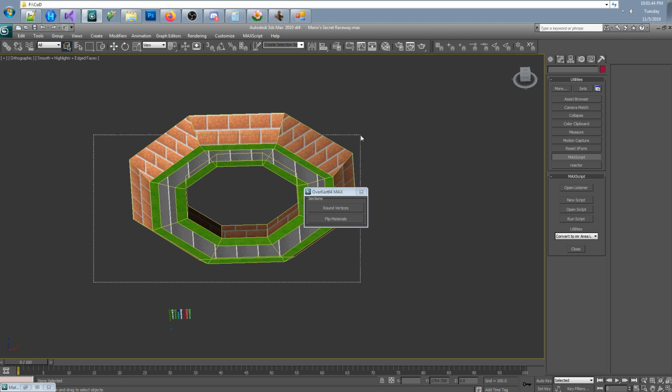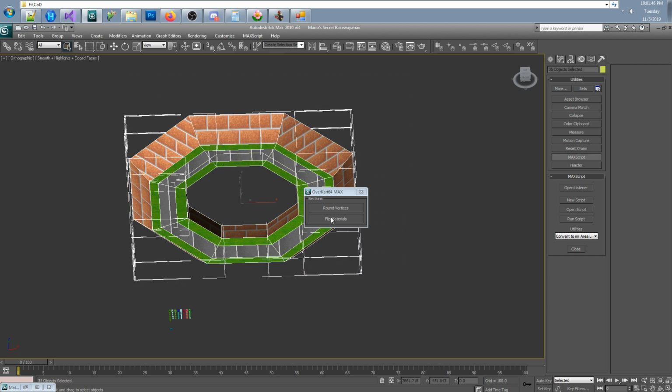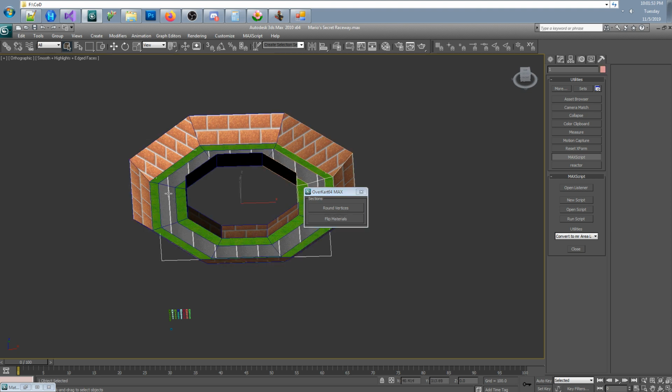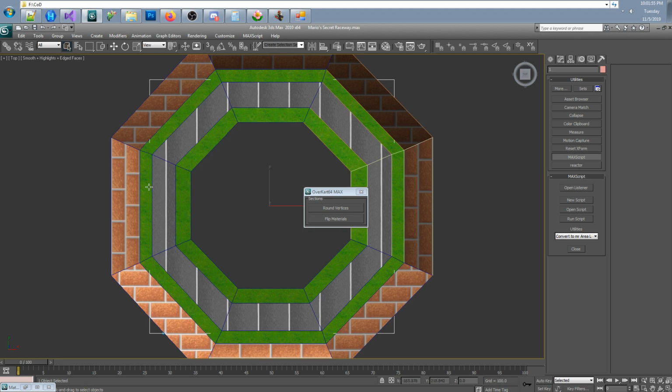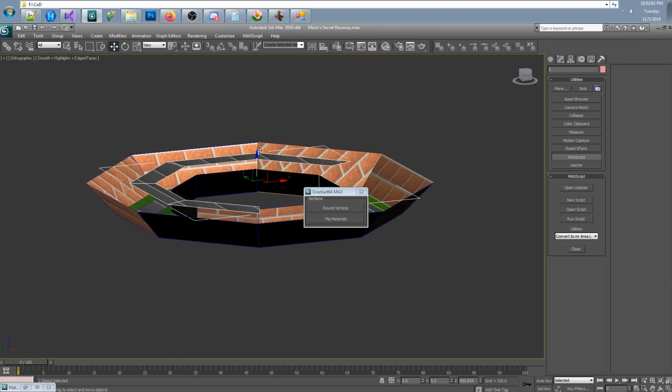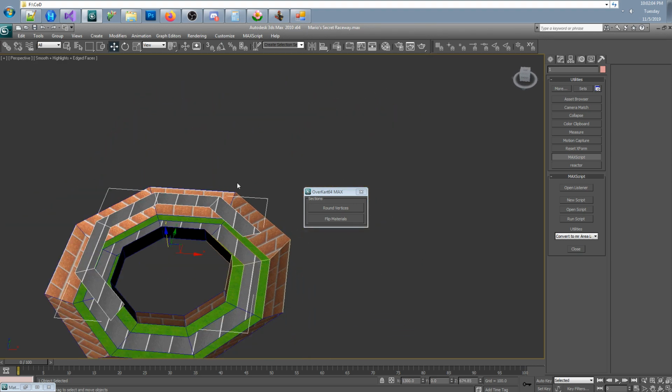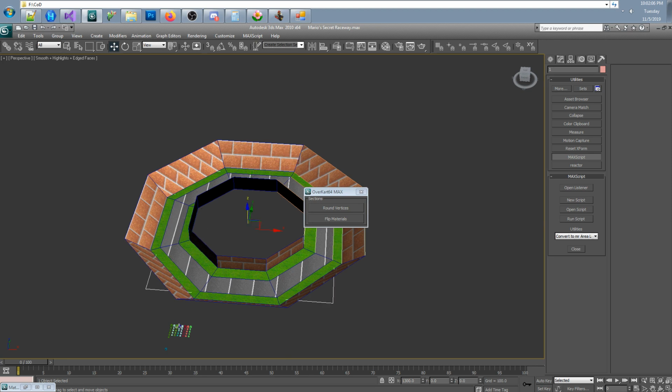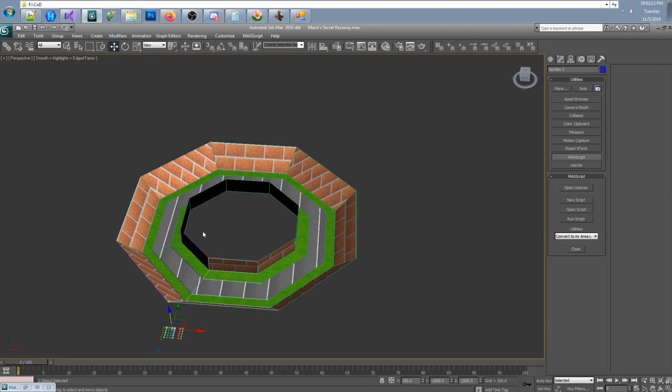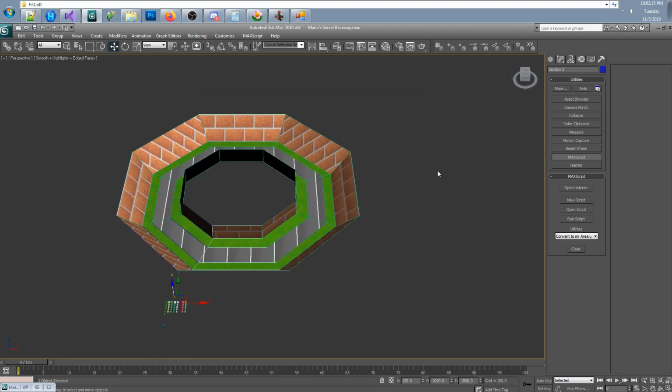So we'll hide those first, select these, and split the materials. You'll notice they are renamed just as before to the materials, keeping the same geometry, and again, still remaining linked to the parent nodes. That's the hard part.